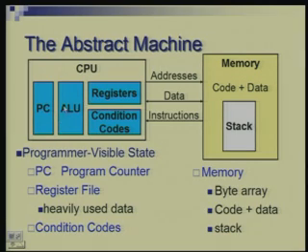Typically, after an operation is done, there are some condition codes which are set. Okay. These often could be part of the register file itself, sometime in some processors these could be separate, and these could be used subsequently for decision making, and that is what helps in providing branches and loops, as you know in high level languages.